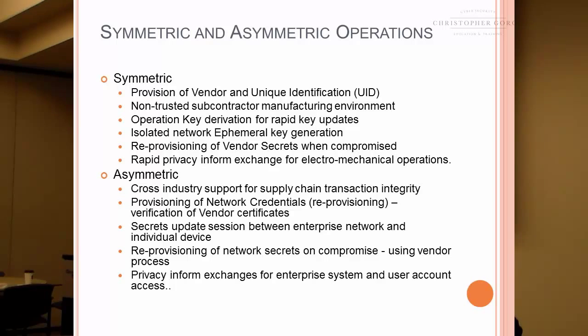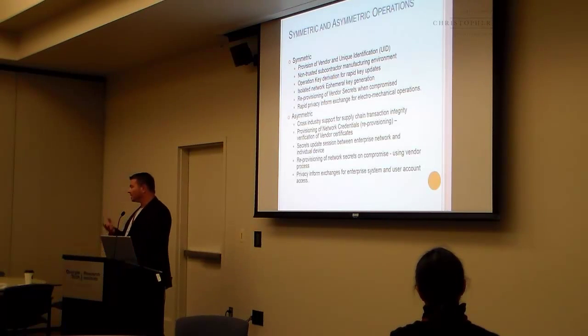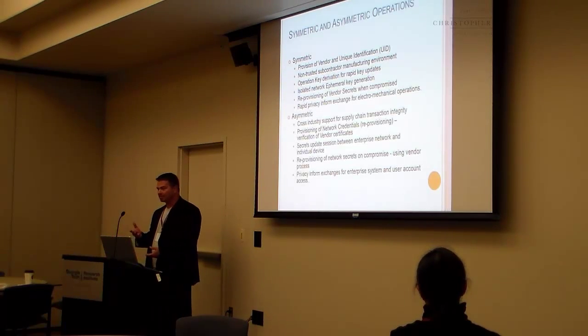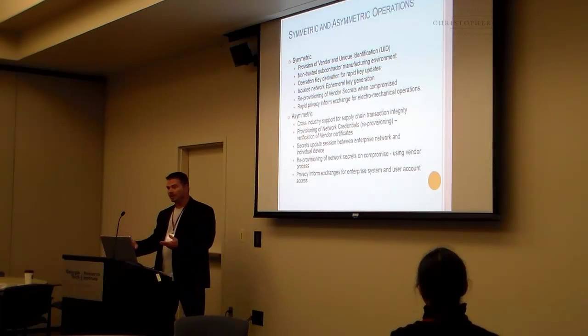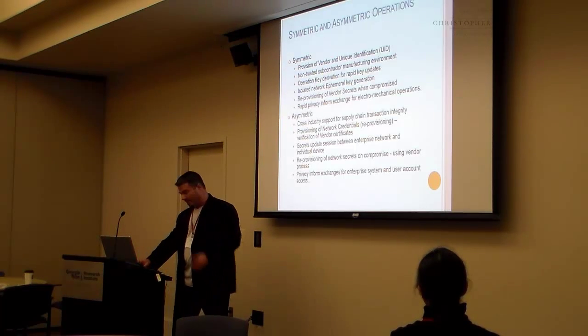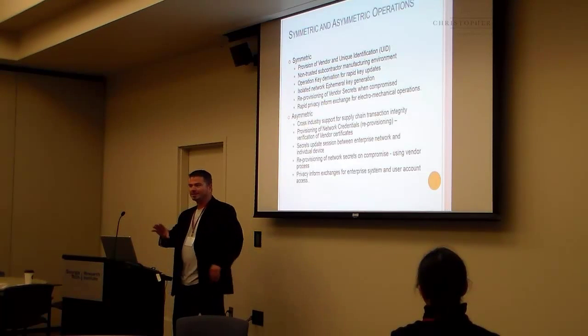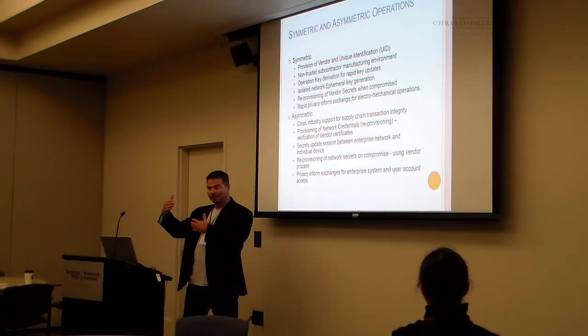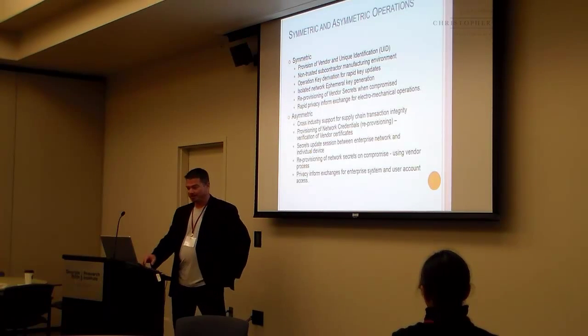Privacy exchanges. Another one where asymmetric works, you wouldn't think about it, and I don't have it on here, is in the initial boot verification on the onboard system trust. Because when you're starting up a system, you're tolerant until it comes on the network to its operation time. So you can use an asymmetric algorithm there. But this just goes to show why I say that you need both in here, because at different places, every device has different timing requirements.